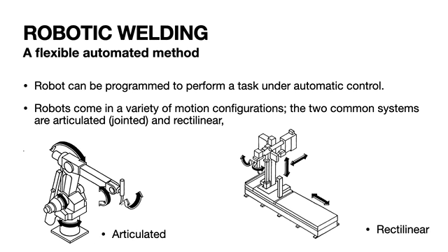There are basically two types of motions associated with robots. The first one would be articulated and the other would be rectilinear. Articulated means it would be hinged, it can have motion in all the 6 axes, which I think you will know. I will discuss it in slightly more detail in the coming slides. So one type of motion would be articulated. Articulated enjoys almost all the degrees of freedom, whereas in rectilinear there is a restriction in one axis movement.